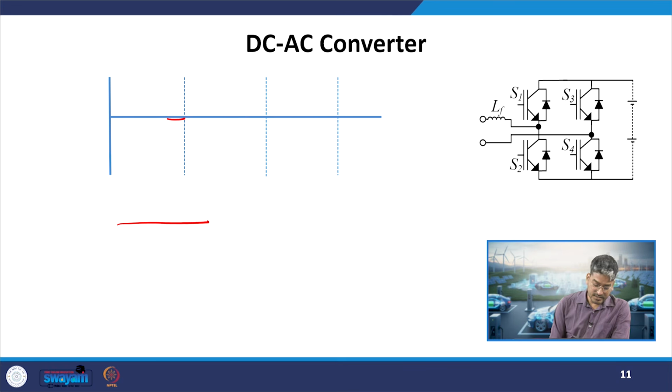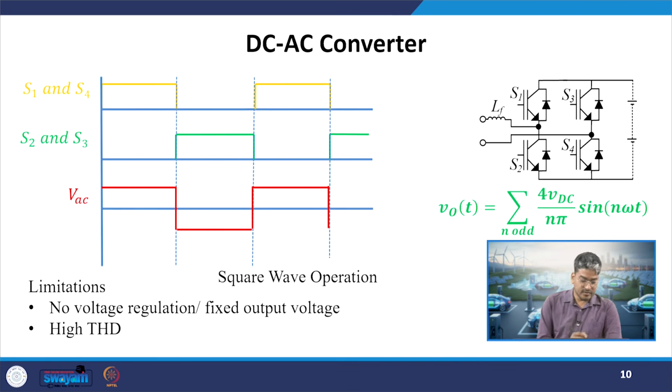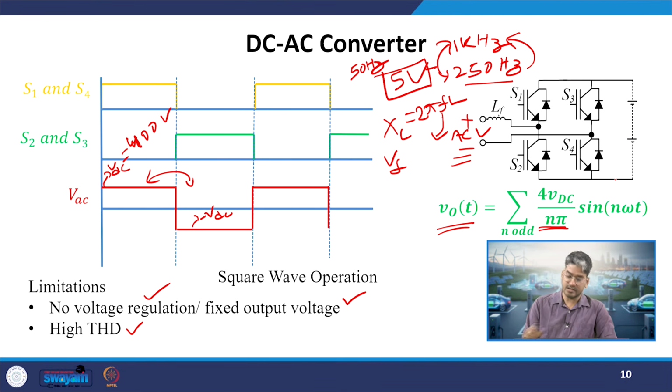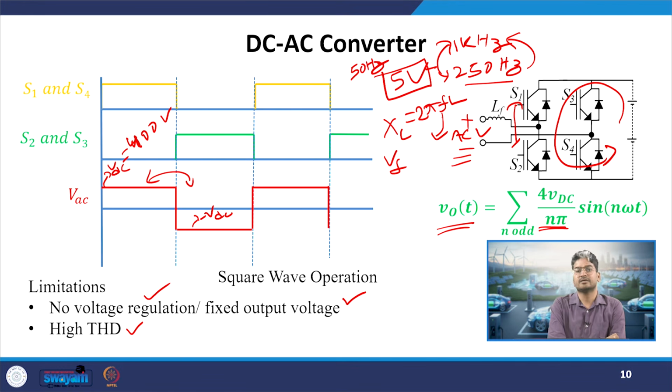Okay. So, what was the other issue with our previous method? We had complementary operation, that is, whenever S1 was getting off, we were turning on S2. In the previous case, we did not have the advanced gate drivers. So, this was creating an issue of short circuit. What is a short circuit? If by mistake S1 and S2 turn on simultaneously, I will lose control of the circuit, because we will have a dead short circuit over here, because the entire leg has been turned on, or the on-state drop, if neglected compared to the DC supply voltage, gives a dead short circuit. So, we will have a huge amount of current and the circuit will be damaged.